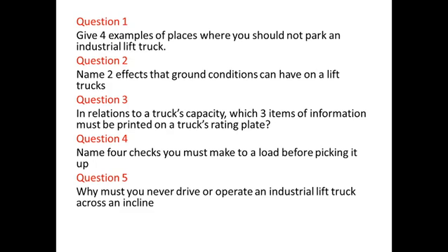Question 3, in relation to a lift truck's rated capacity, what 3 bits of information must be printed on a lift truck's plate? This is something that we saw in the previous presentation. Things that were highlighted were the maximum lifting capacity, the maximum height at which the load can be lifted, and also the maximum load center.